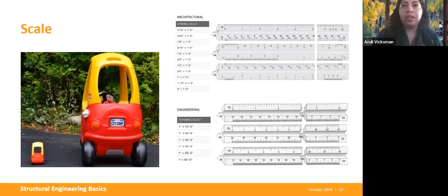For the rulers that are here, it typically will show the scale on the ruler. I'm not as familiar with the architectural rulers, but the engineering scale, the bottom one looks like 1 inch is 30 feet based on the 30 there. The middle one's 1 inch equals 20 feet, and the top one's 1 inch equals 10 feet. And that helps you see that there. Was that your question with the rulers? Okay, and then it will say that scale on the plan like Enrique talked about, and that helps you know what scale your drawings are actually to. Any other questions?